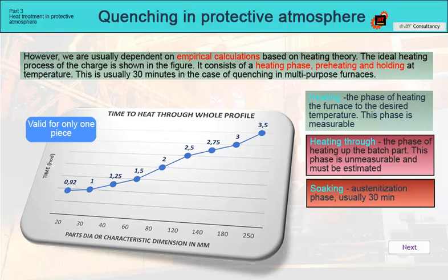The diagram should therefore be taken as a guide, and applies only to one ideal piece. To determine the heating time of the entire batch, it is necessary to take into account other parameters, but, above all, the results of the evaluation of the resulting structure, hardness, or carburizing depth of already tuned processes, and either apply the process parameters in full or modify them and adapt them to the new batch. Since heat treatment is one of the so-called special processes, which are characterized by the fact that the path to ensuring the customer requirement can be different, the result will be important to us.